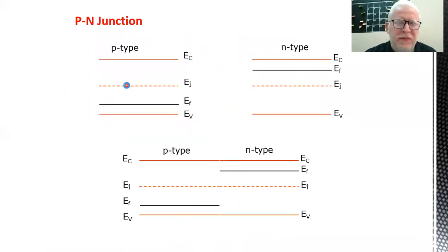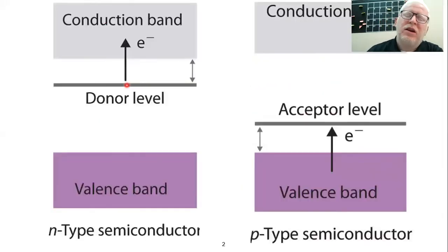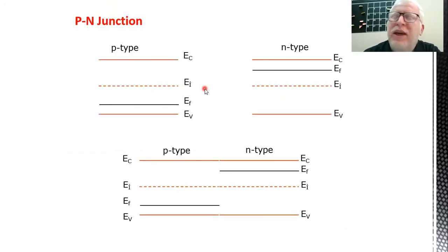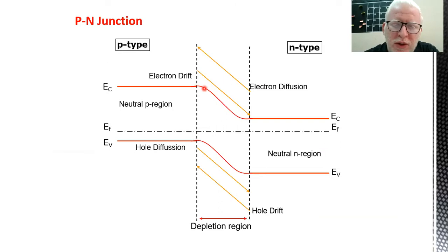Perfect. So, if you remember, in the previous part, we discussed the combination of the n-doped region and the p-doped region in what's called the p-n junction. First, we proved together that the Fermi level, as the reference for thermodynamic equilibrium condition, should be totally flat whenever there is no applied voltage to the device.